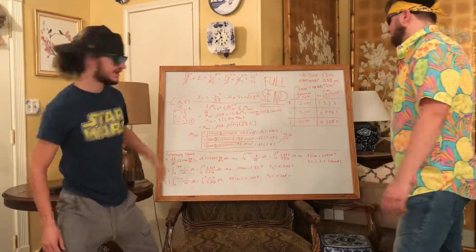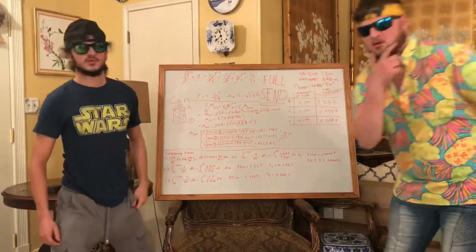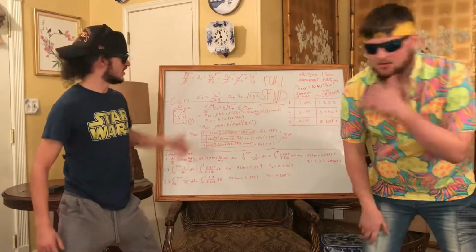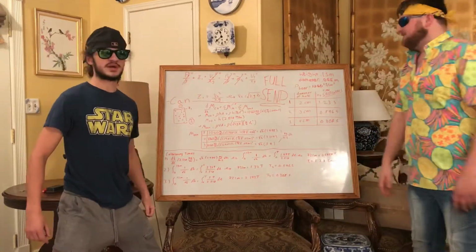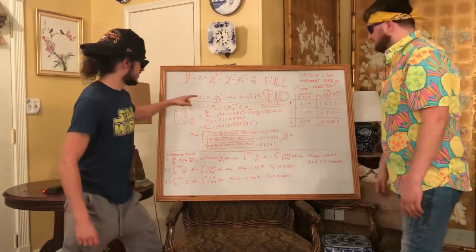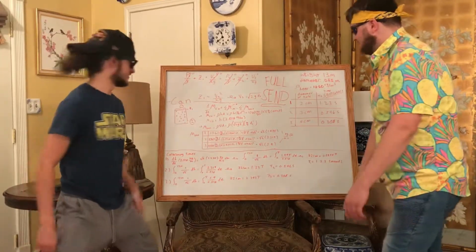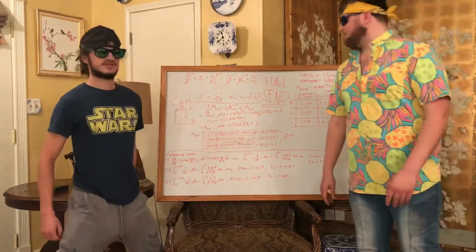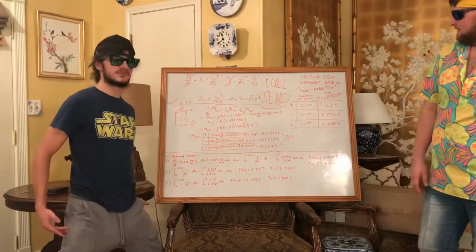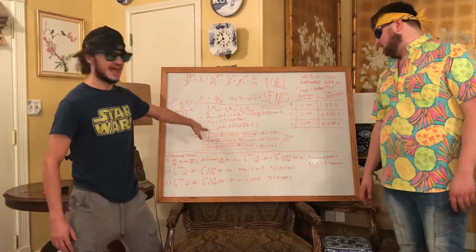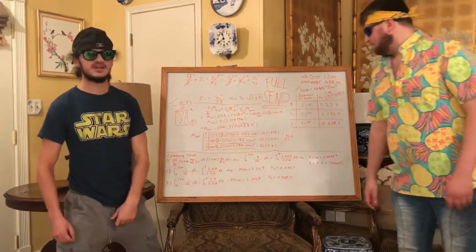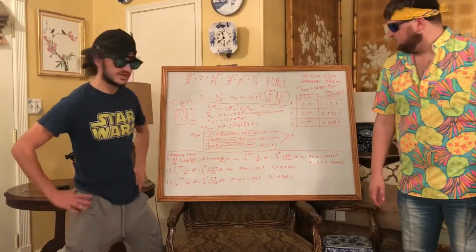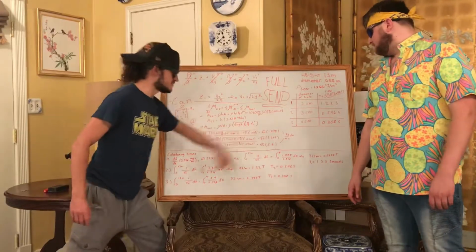The mass of the control volume equals rho H A, where rho of beer, which all Chads know, is 1,060 kilograms per meter cubed, times the height times the area. We come out to m_cv equals H times 2.518 kilograms per meter. And we got m dot out equals rho V A, which we calculate for each of the 3 diameters, and we get these values here.